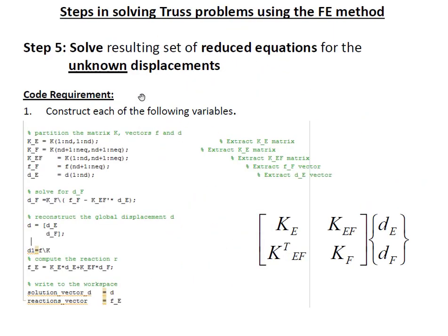So after the assembly, you call the solve_dr file, which is the fifth step of your solving process in finite elements. Recall that we had defined an nd variable that identifies the number of prescribed displacements. And in this case, since it was easy to group the essential degrees of freedom and the free degrees of freedom, we can solve this problem using the partitioning approach.